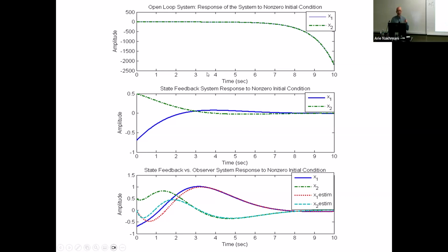Now, in closed loop with a controller where you have access to the state X of the original system, this is how the X's will converge. So I'm designing the location of the poles at negative 1/2 plus minus 1/2 j, right? And then connecting to the original state X, I get that type of convergence. So converging in probably about 3 seconds or so. After 3 seconds, it's more or less converged to 0 from the initial condition 0.5 with 0 input. This is convergence from initial conditions.